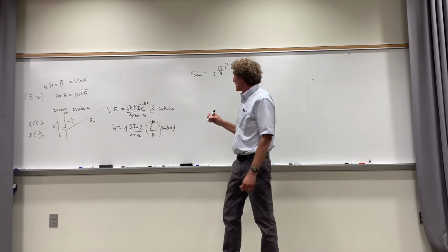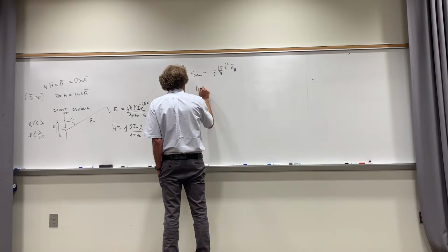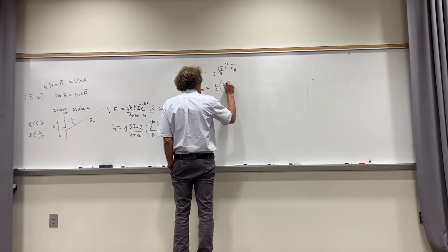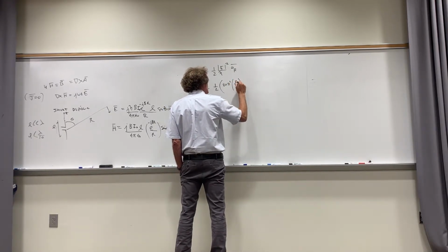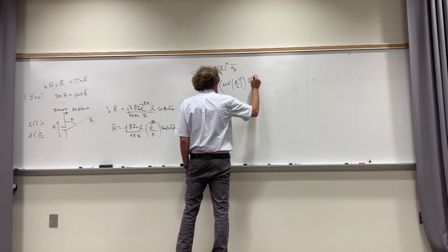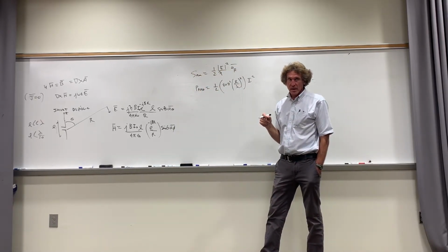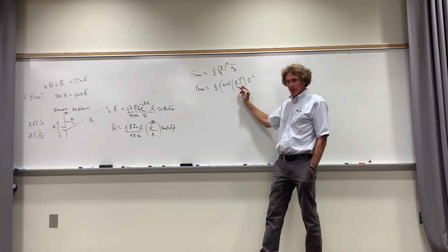Then, after that, you'll notice the total power radiated is 1/2 the radiation resistance, 80 pi squared, times L over lambda squared times I squared. That's the total power radiated, right? And if we want to, we can calculate the radiation resistance, but it's right there.